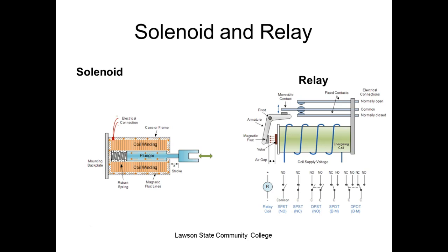Well, what are they doing? Your cell phone is being picked up by Bluetooth or Wi-Fi, whatever you're using, and then it's energizing a solenoid. The solenoids are controlling contacts, and the contacts are opening and breaking. So now we can control contacts with electricity instead of manually controlling them. As soon as I turn it over to electricity, I can control electricity, so we can have automation. So what a relay is, it's nothing but a solenoid that controls contacts. That's all it is.